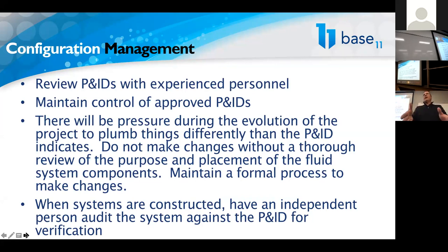You're absolutely right. You're going to need to go further back on the pressurization system side at the very least to see where things segregate and make certain that you have redundant ways to make sure that you can't get oxygen going back to your fuel system and fuel going to your oxygen systems. How you manage the documentation of those plumbing and instrumentation diagrams and so forth, if you happen to be in a situation where you're just starting and you're building up your system for your rocket program, I would put it all in the same document.